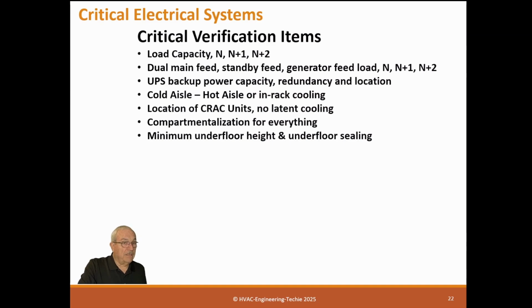Maximum underfloor height and underfloor ceiling. Now this may have changed a little bit, because when I got the tier ratings from the Uptime Institute, we were heavily into data cable. The reason the floor height rises is because there's so much cable underneath the floor that it restricts the airflow, because the CRAC units normally flow to the computers under the floor. Nowadays we're using mostly fiber, and a lot of that fiber is above the units, not below the floor. So they may reduce the floor area if they don't have any cabling down there, but I'm not sure about that. We would have to see what's currently in the industry.